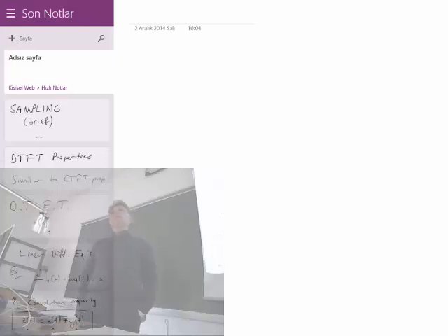As you see, we didn't cover a lot of things from this sampling chapter, but for me it is finished. There are only two fundamental issues that you have to be careful about in terms of this sampling business. One of them is the knowledge of the Nyquist rate to avoid aliasing. So Nyquist rate, sampling frequency, aliasing, those concepts are the first important issue that you have to be aware of.